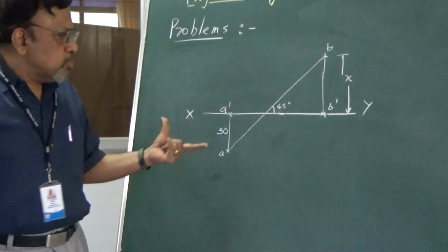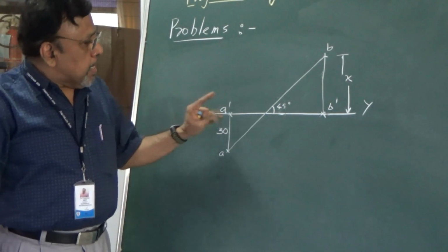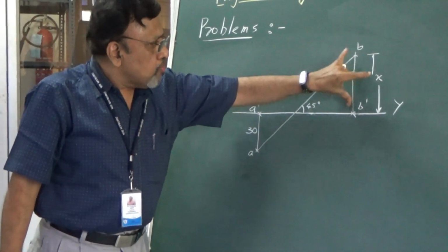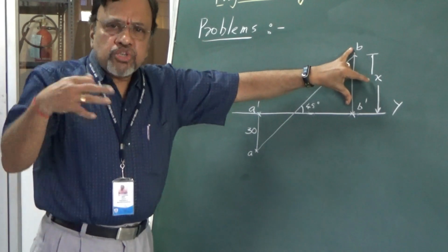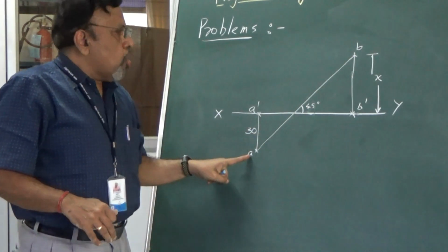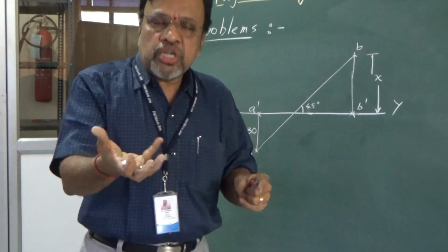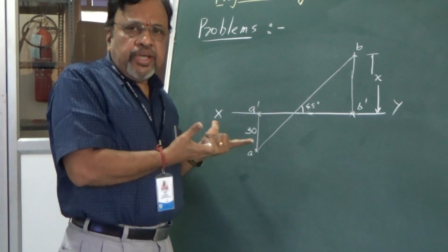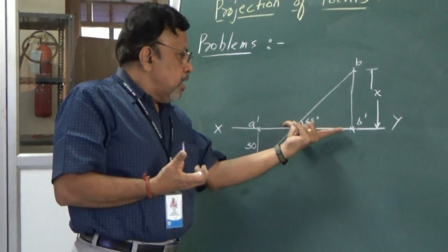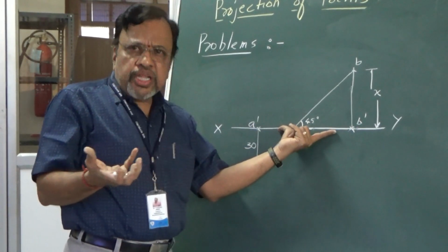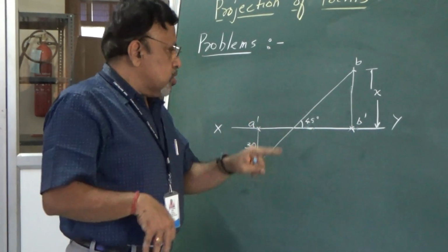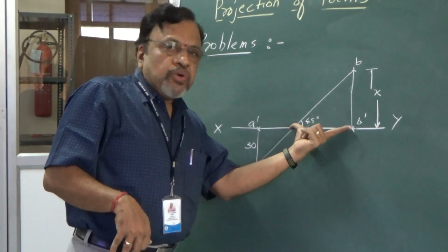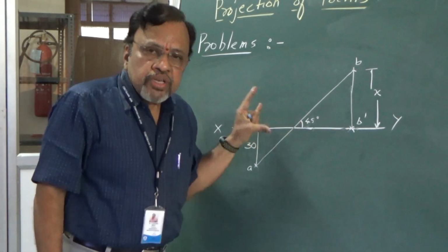So that's all. As you can see, I have given one data, but in the previous problems I would have given the distance of the point B, then also told you to join their top views and find their angles. Or I can also say join AB. But in this particular case, if I join AB, it is an XY line. Why? Because we know that the front views of both the points A and B are on XY, or on HP itself. Is it clear?